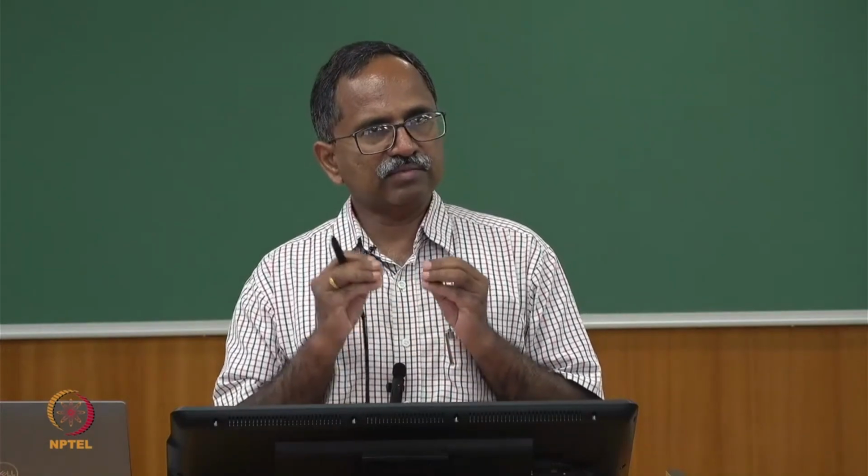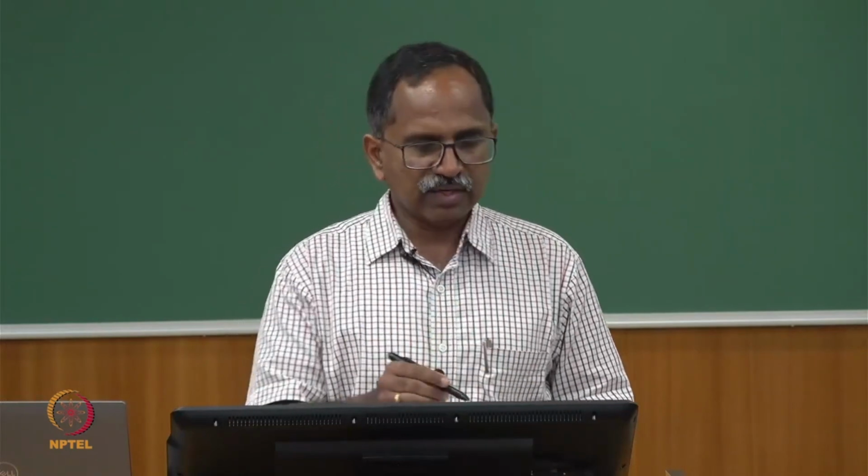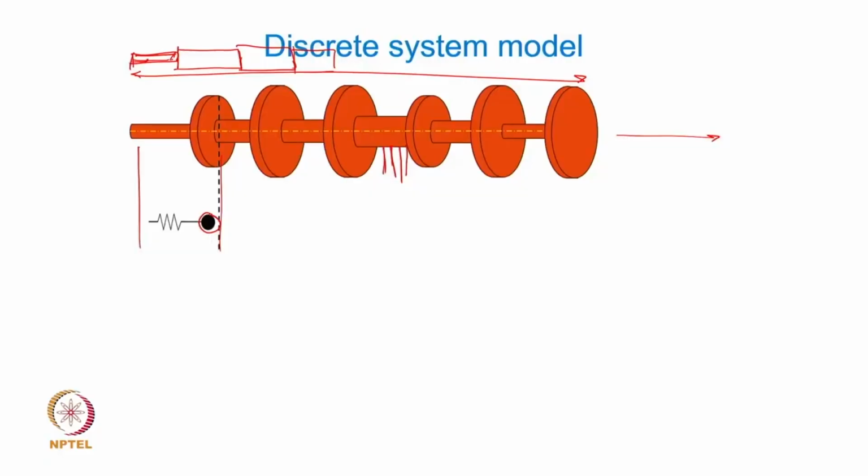You treat each segment separately, and vibration will happen only if you have a mass and a stiffness. That means there has to be an element for storing strain energy and an element for kinetic energy. So what we do is, each segment will have a lumped inertia element and an element to store the strain energy. So you have a stiffness and a mass or inertia element, and together they constitute a segment. And when you couple all such segments one after the other, you get the original system. That's the philosophy here.